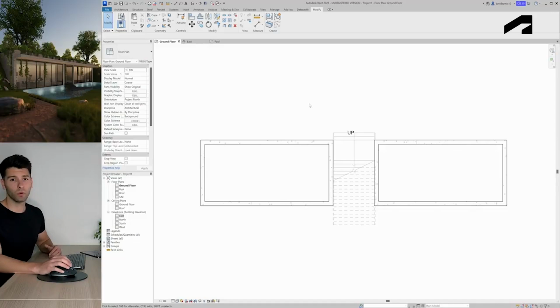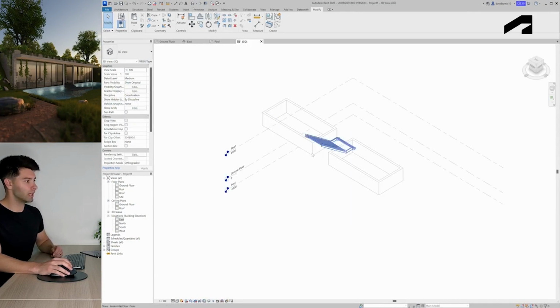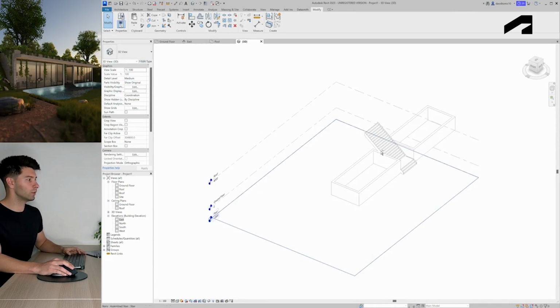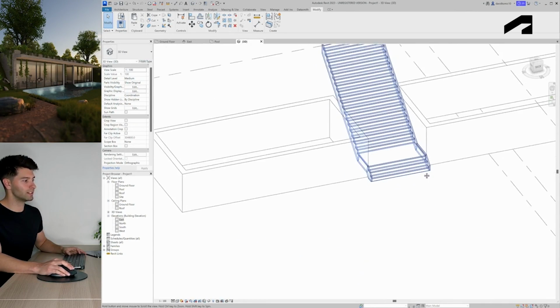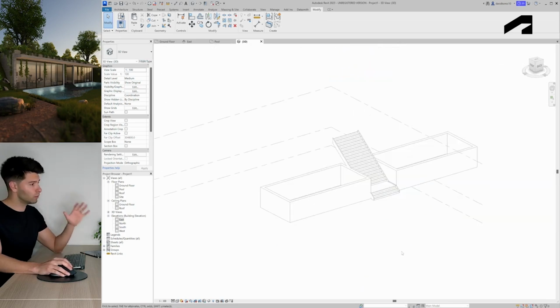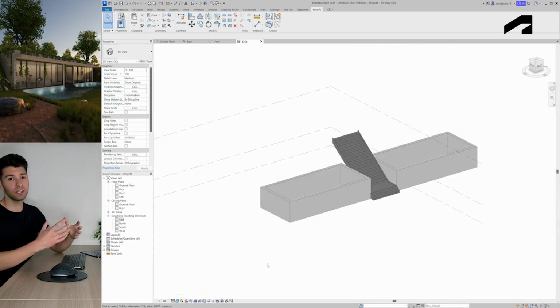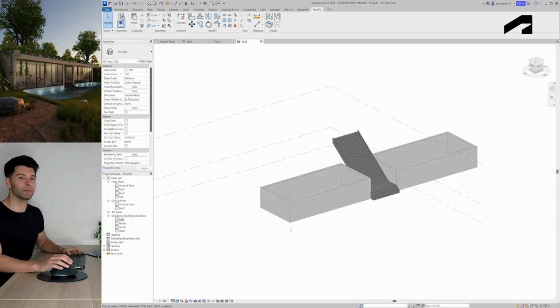And now let's check out what we've done in 3D already. If we come up to the top, you're going to see our default 3D view. And holding shift with our scroll wheel, we can scroll around to see what we've created. Revit by default will show you this black and white line feature. If you come down to the bottom, you're going to see the visual styles. If we click on that and just go constant colors for simplicity, we're going to see something come to life.